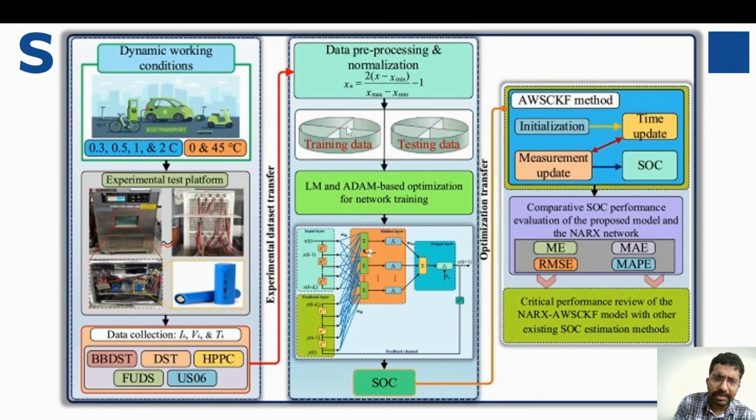So this is how we develop that ANN model or toolbox which can be used for an advanced BMS. The experimentally validated, HIL-based data should be split into training data and testing data, trained and tested, and then we will be able to implement them in real time based upon the error observed: mean error, mean absolute error, root mean square error. Those things will help to improve the next models.